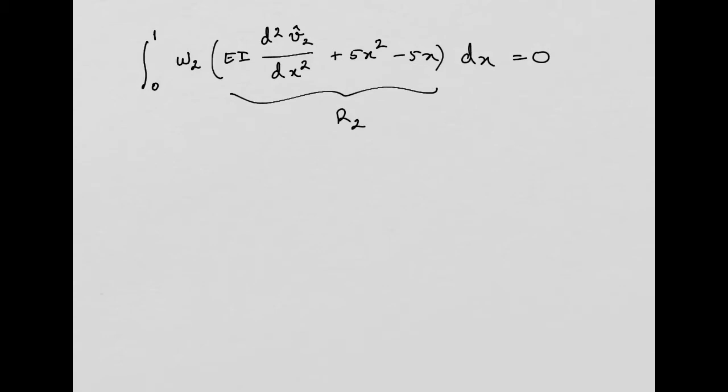We want to minimize this residual, so we affect this residual with a weighting function, which, if you use the Galerkin method, is going to be equal to the shape functions. This is a very quick review. I can write here Galerkin's method.